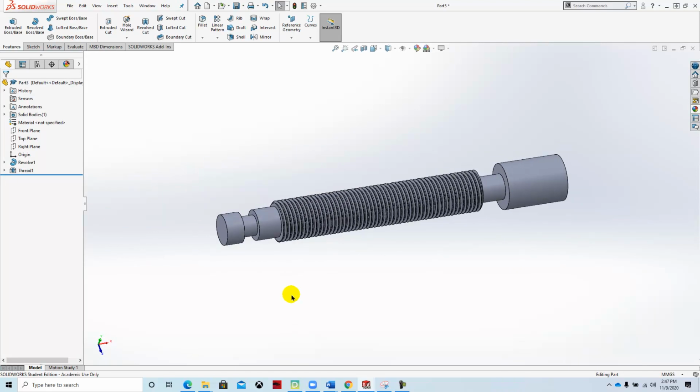And now we have a threaded jack screw that we can actually print. A lot of times what I'll do is I'll print these, and then I'll run a metal die over it, or you can just get a nut, and thread a nut onto it, and it'll straighten those threads out. Because remember, 3D printing prints in layers of plastic. It's 0.2 millimeters, 0.3 millimeters, depending on how you have the fineness set. So it often needs to be tweaked.